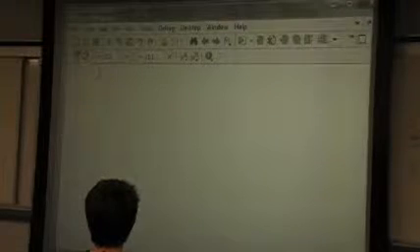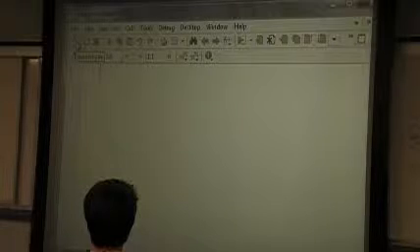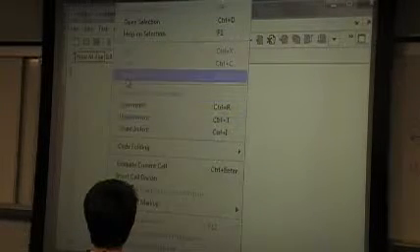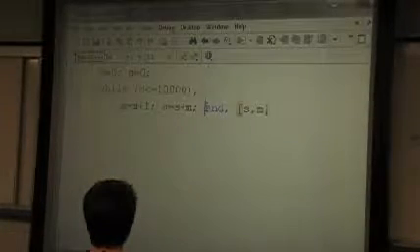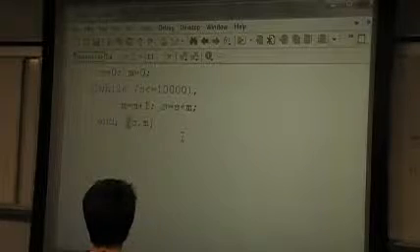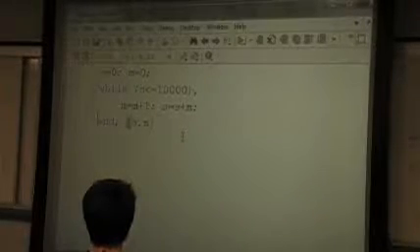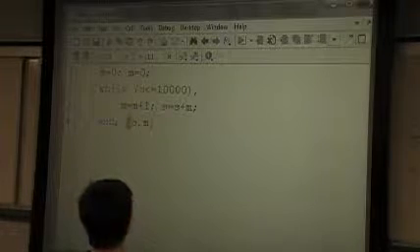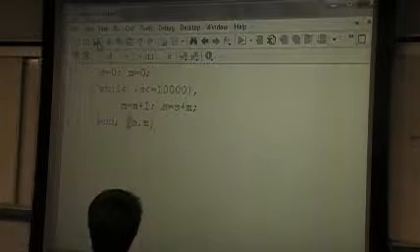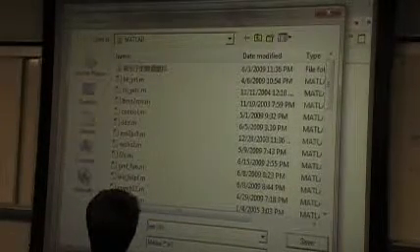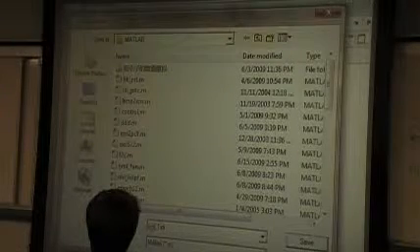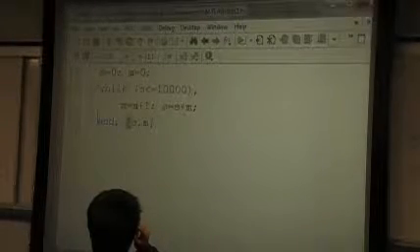We can open a Matlab file editor and copy the commands to this editor. And we can use carriage returns to make it look better. And here, if we click this icon, we will save this program as test1. And now we have the first Matlab program called test1.